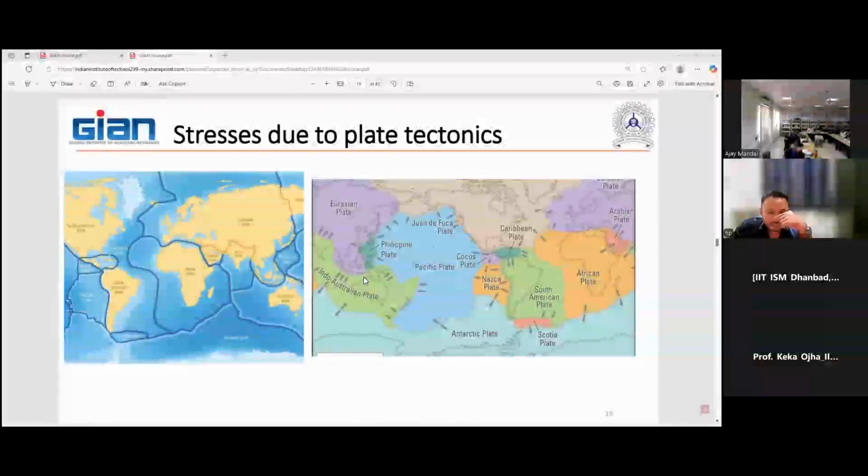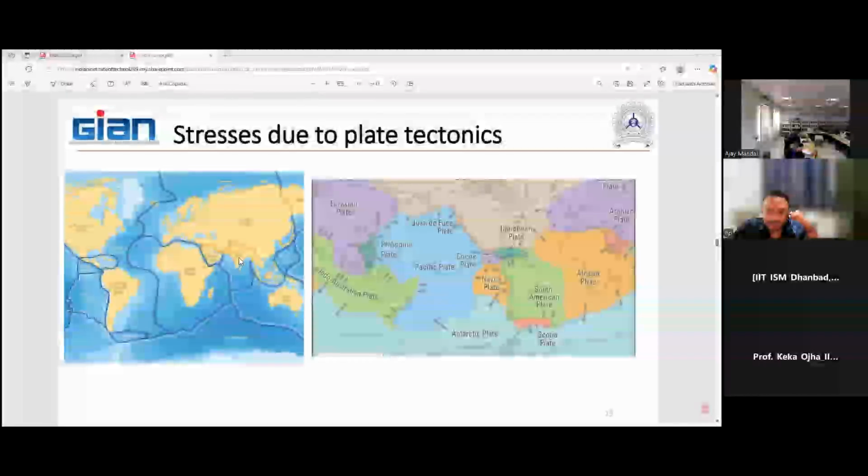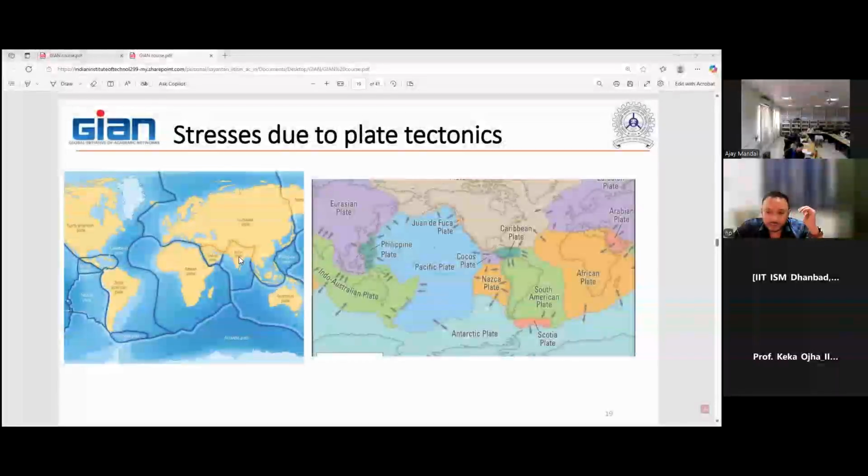Those are SH min and SH max. Those different horizontal stresses are mainly coming from plate tectonics, because plates are rubbing past each other, pulling apart from each other, or pushing against each other. That is where you get the differences in the sideways stresses, SH min and SH max, and they are mostly unequal in most cases.